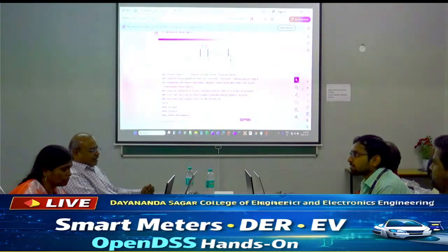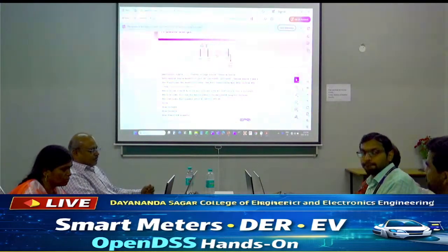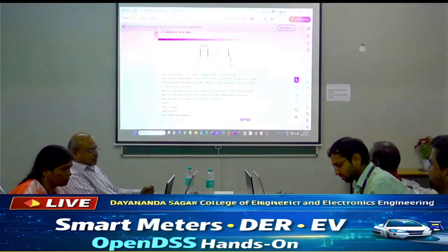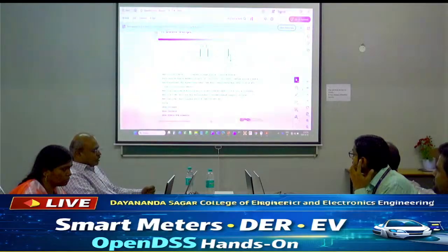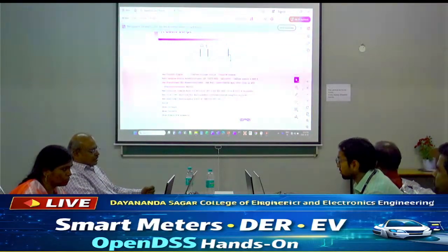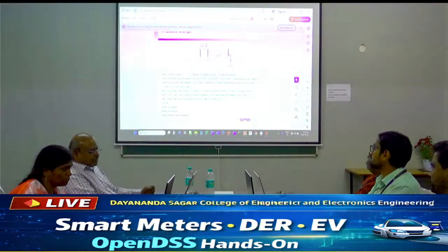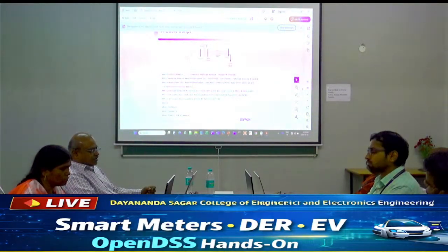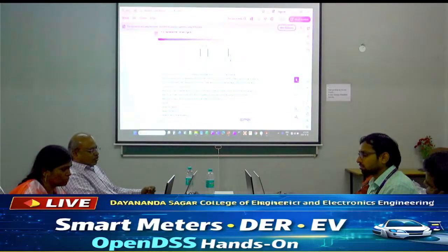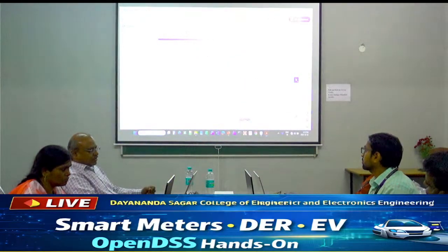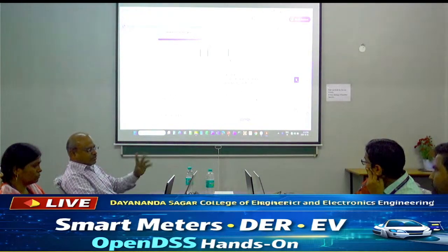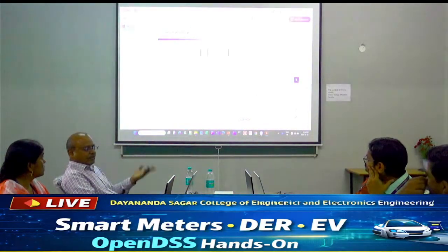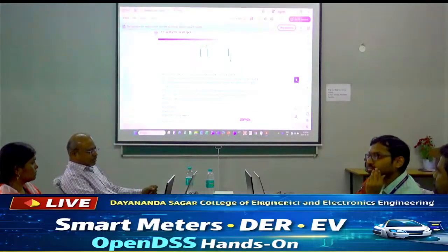And then after that you define lines. So now for this line we say okay, what are the two buses? Bus 1, what is this side, and bus 2. So here it is the source bus and here the load bus is there. So the sub bus and load bus, that is what is mentioned. This is the line code, defined here. And what is the length? This is kilo feet, but here the length is given as 1 and it is in miles. So it will do all the conversion automatically. Multiple units are supported, as in the user manual, like meters, kilometers and everything, a lot of things are there.